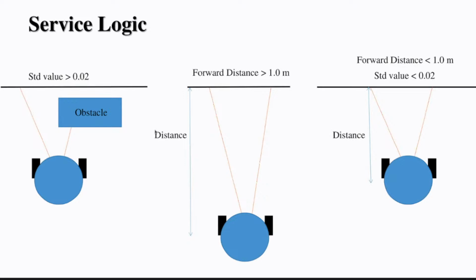I want to get the closest possible. This value of 1 meter is after testing a lot, and with this parameter I can be sure that in any position of this circuit, of this environment we have, the robot can find some wall within 1 meter distance, and he's not going to take a wall too far away.